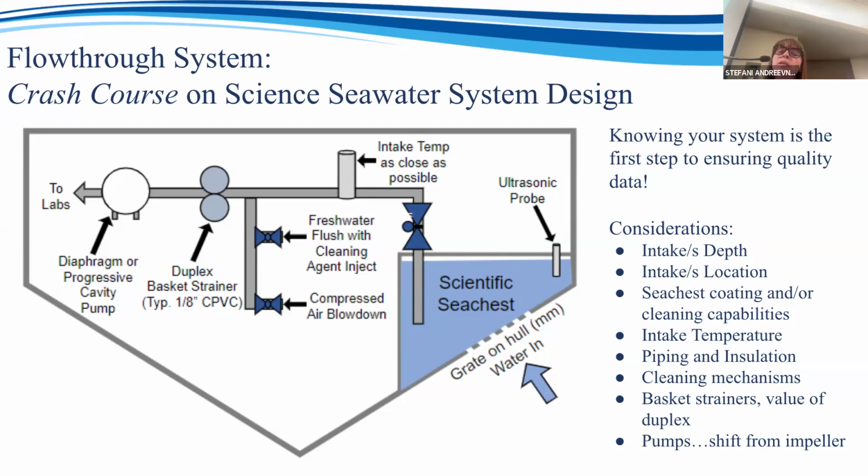And again, this is just showing, okay, you typically have a grate on your hull with a mesh size of a few millimeters, so you don't suck up any logs or anything. It goes into a scientific seawater chest. With scientific seawater chests, it's pretty interesting in terms of design. Some of them are now being delivered with ultrasonic probes for cleaning. And there are things you want to consider there. When are you running this ultrasonic probe? Do you know what an ultrasonic probe does?